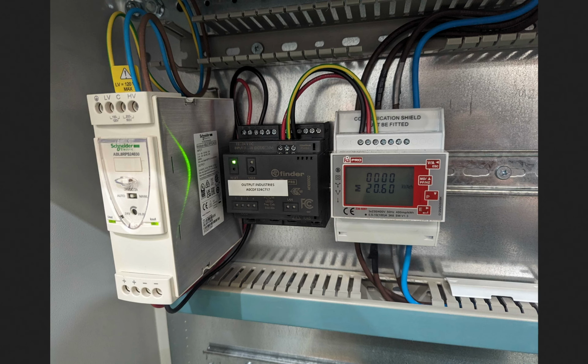It's doing more than that in terms of capturing all of these different signals, potentially from multiple different machines, and talking to energy monitors. Because we're using the Modbus protocol, these energy monitors can actually be daisy chained to a single device. So a single unit like this, we could daisy chain up to 16 energy meters as well. So we have quite a few customers that are using these from multiple machines from a single device, all again being wirelessly transmitted back to us. So between this device, the energy monitor, and the tablet device, that's our standardized way of doing that automatic data capture from the shop floor. It's working very well so far.